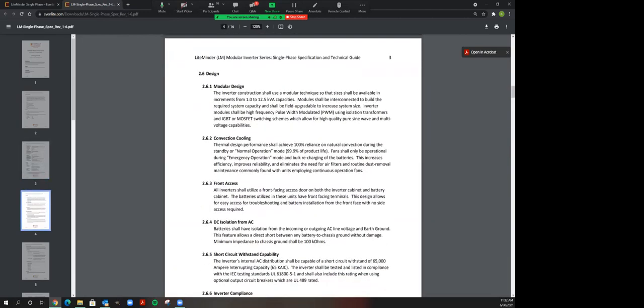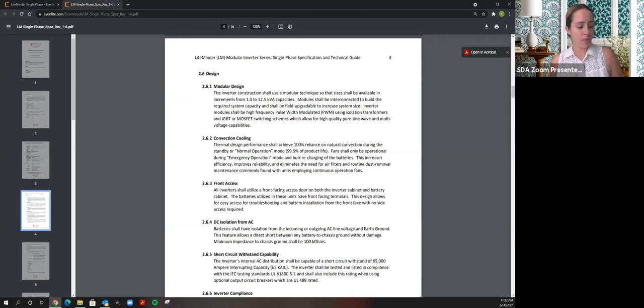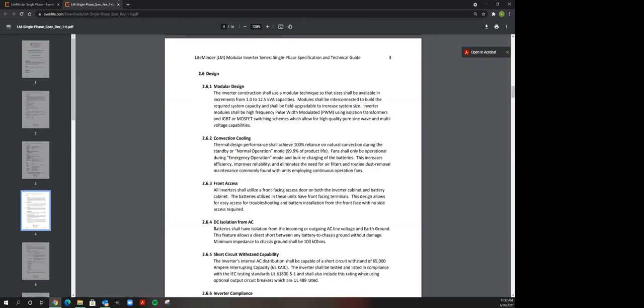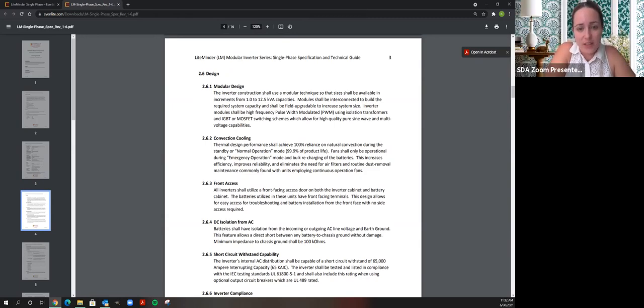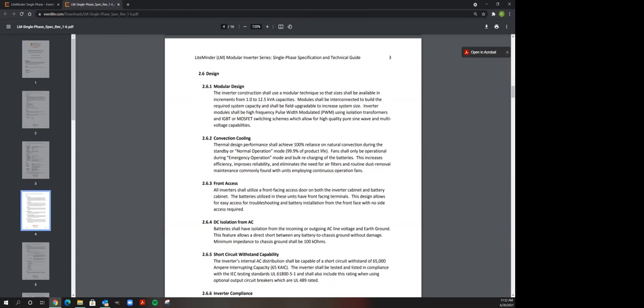I could talk about our convection cooling. We have convection cooling. Other manufacturers use fans. Because we do convection cooling, there are no moving parts. Therefore, you don't have a failure point. If you were to specify one of the largest names out there, that starts with an M? I cannot confirm or deny that. Got you. If you were to specify their inverter, they have fans in there. Well, what happens if those fans fail? Batteries overheat, batteries go into thermal runaway, and you have a potential meltdown on your hands.